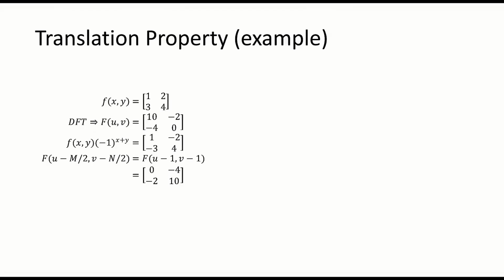For example, if I directly take the Fourier transform or DFT, I will get something like this one, which means that the low frequencies are on the edges, and the high frequencies are in the middle. However, it's easier to design a filter if the low frequencies are in the middle. So in order to do that, I can use the property of Fourier transform, which says that shifting in the Fourier domain is actually multiplication with an exponential. And this shifting is a special shift by half of the length of the signal. Because of that, it reduces to this thing, which is very easy to compute.